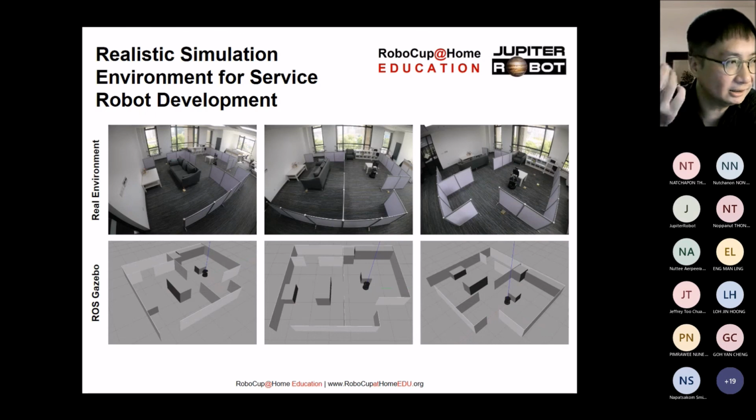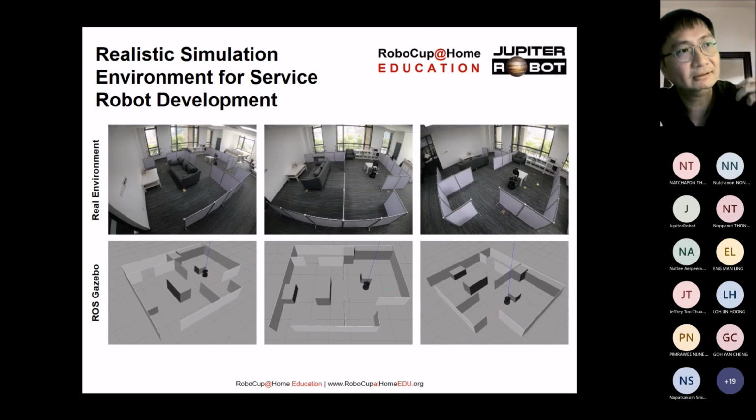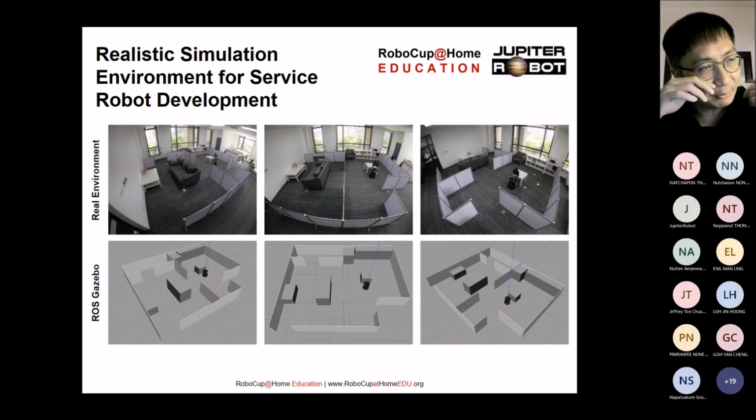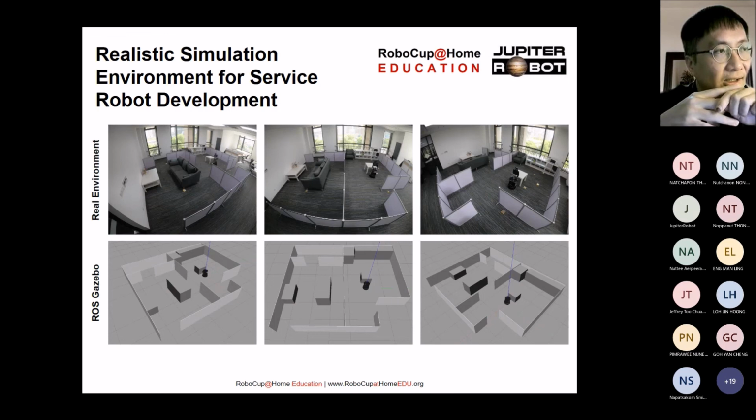Yeah, that is the reality, that you need a lot of resources, especially when you run Gazebo and you run RViz together. Both require a lot of resources to run. So when you use VMware or VirtualBox, unless your machine is very powerful and you can give a lot of resources, the minimum I think you're supposed to give is 2 CPU with 4 gig of RAM.